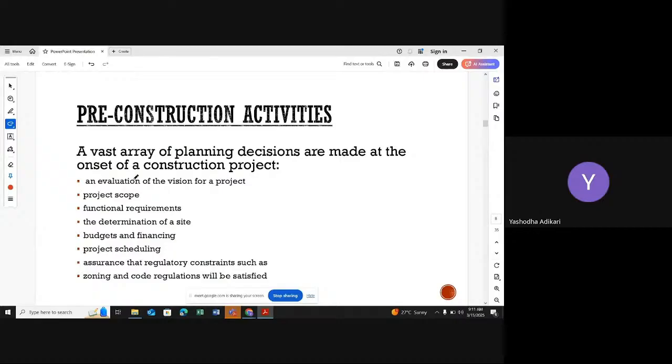So that's the first thing. During the pre-construction stage, you have to take 100% completed drawings. Not only that, before going to the construction activities, as a client, you can request a BOQ, or the accurate cost estimate for the project. Previously, we were doing some assumptions, like, I can spend 10 million, please design it for 10 million. But before going to the construction stage, as a client, you can request a BOQ, bill of quantities. Then you can check the total cost of the building. With those confirmations only, you go to the construction stage. Otherwise, you can't start the construction activities with confidence.